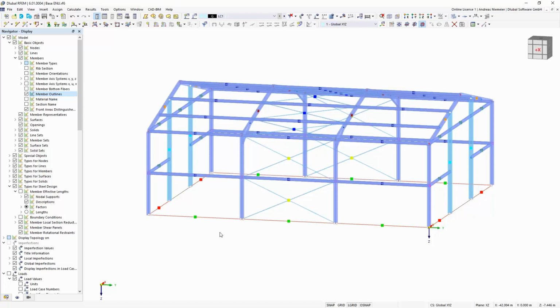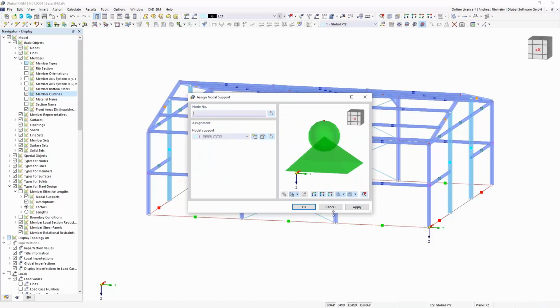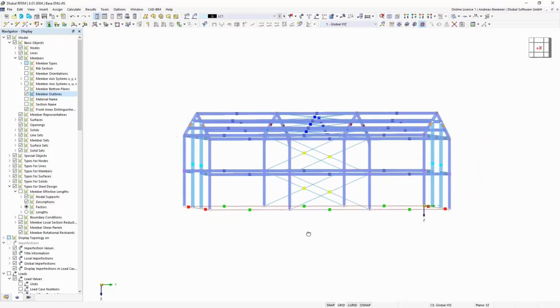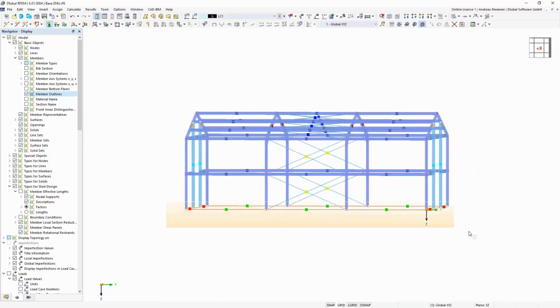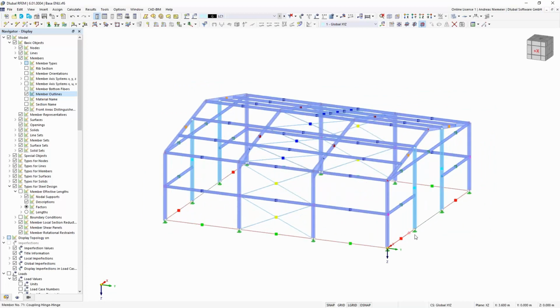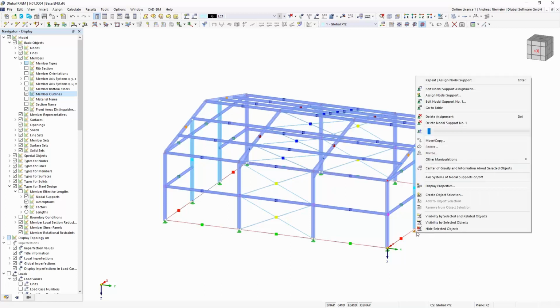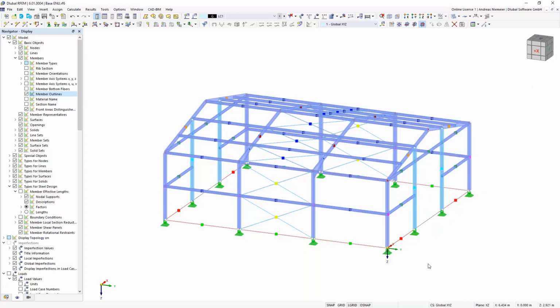And support was the keyword we place here also on the bottom legs of the members, a nodal support, a hinged nodal support, only by drawing here a window about it. And you see the program draws a picture of the symbols, and if you have the feeling they are too small, you get now here such a spin button, a horizontal one, where you can specify the right size of these supports. The same is offered for loads.